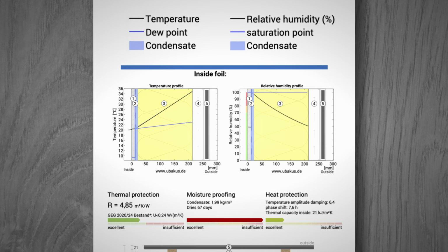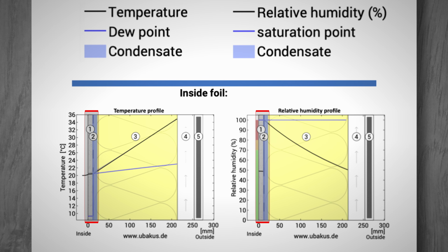The primary purpose of the Glaser method is to identify potential condensation points in building elements, thereby helping architects and engineers design structures that minimize moisture accumulation. It aids in selecting appropriate insulation and vapor barriers to ensure the longevity and healthiness of buildings.